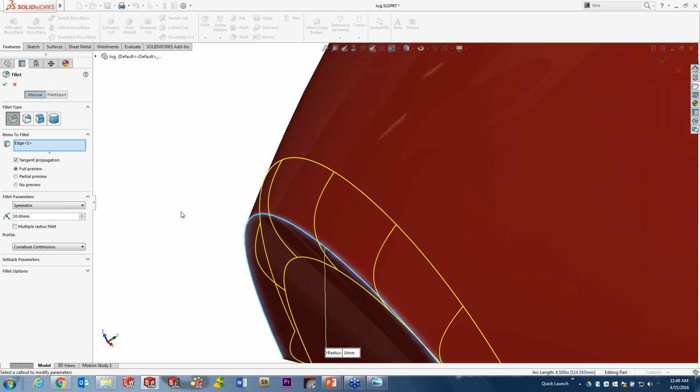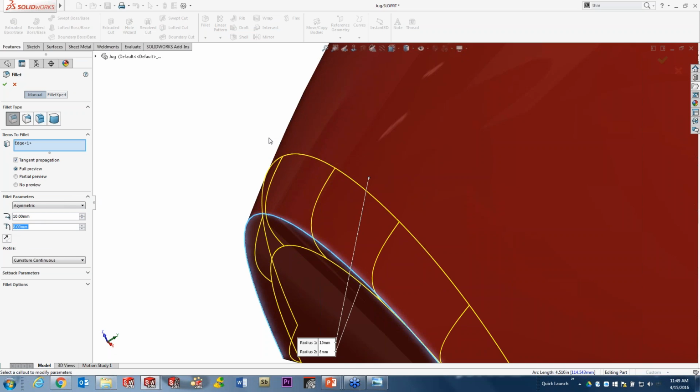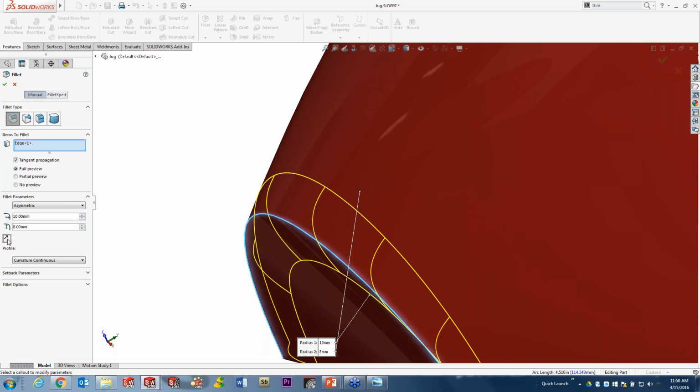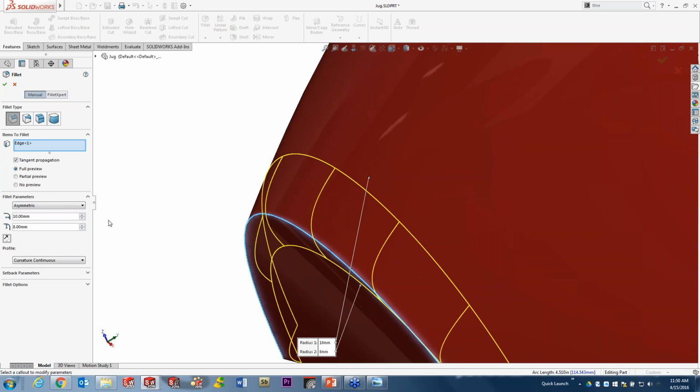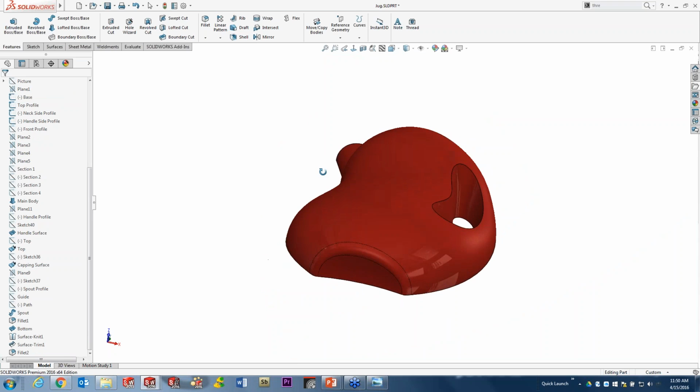Now with that, I can also go ahead and take this profile and change it from a single radius, we call it symmetric, to something called asymmetric. Now asymmetric very simply means I have a different distance in each direction. So I can have 10 millimeters going up the side and 8 millimeters going around the bottom, or even toggle those profiles and switch their direction. But no matter how you slice it, this fillet blends very slightly as it comes off of that face and then turns more drastically around the corner as it attacks this bottom face with another Class A blend. We say OK to that, and we get a fantastic blend between those two complex faces.